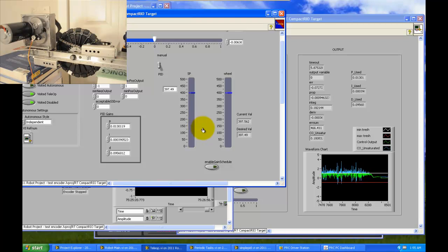That wasn't too bad. There were some hiccups in the beginning, and you can see this is what our controller did, and it came down and it stopped. We ran to 400, and we got there, and there was a little bit of undershoot, so it slowed down, and then it went there. It looked similar to what Simulink thought the controller would perform. But you saw the hiccup that happened in the beginning? That was because of this high frequency noise. Let's try to do it in reverse. Like you can see, we have a nice undershoot. It's going there, taking some time to get there.